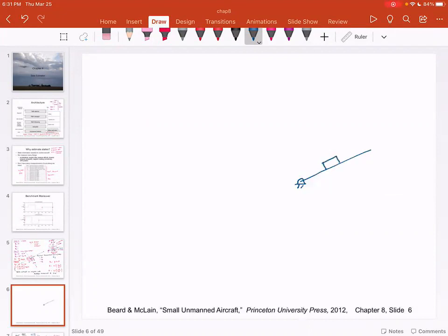You have an IMU, and now this is going at a slightly higher speed. So as soon as we start doing this, our logic theta is equal to sine inverse of AX divided by G will not give good results if theta dot is large.